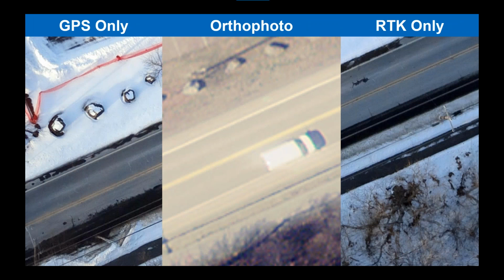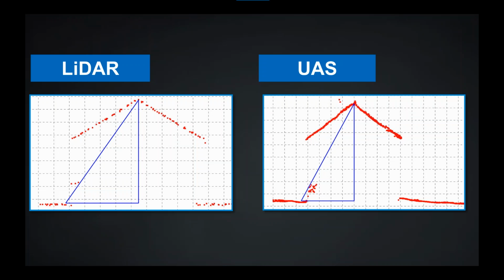Okay, so in addition to orthophotos, we can generate point clouds from our UAS data. These are photogrammetric point clouds, so they're not the same as LiDAR, but in certain cases, especially when you're looking at hard surfaces, they work well. Here we have an example on the left of a point cloud profile from airborne LiDAR of a building, and on the right the same building done from a UAS photogrammetric point cloud. These two building heights are within centimeters of each other. So these photogrammetric point clouds can be very accurate, but we'll see in other areas where you've got shadows and trees and water, the elevation errors can sometimes be substantial, and it's important to keep those in mind.